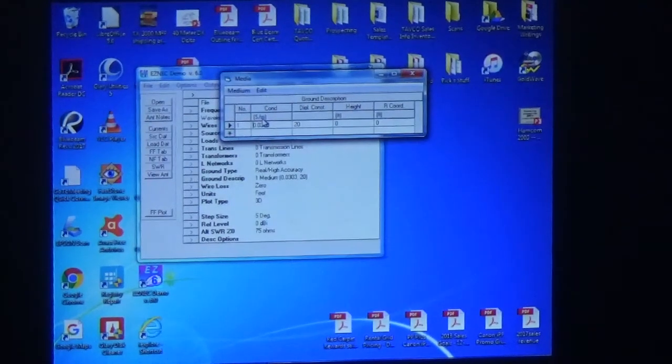One of the cool things is, I don't know if y'all are familiar with Team Vertical. It was Tom Schiller, N6BT. Those guys years ago took verticals and put them at the water's edge. The reason they did that is because when they modeled the verticals at water's edge, they could get that bottom 1, 2, 3, 4 degrees of launch angle. Whereas if you put it over ground around here, you don't get anything until it's 5 or 6, 7 degrees. So they wanted that low angle.